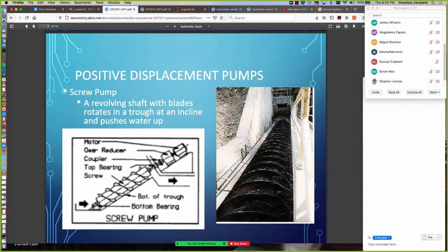One of the operational challenges of these pumps is that usually you would design the PID controller to maintain the water level just below the bearing, so it just catches the bottom edge, and that way the bearing can be kept out of the water and it lasts longer.